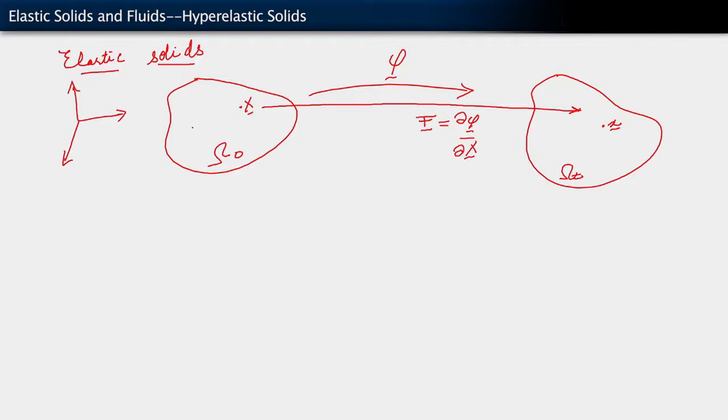We have the notion of various stress tensors that are defined here. Of course, we know that P properly lives between the two configurations, but I'll just put it there. We have sigma, which properly lives here, the Cauchy stress. P is the first Piola-Kirchhoff stress. So I refer to this idea that solids, when deformed, develop stresses.